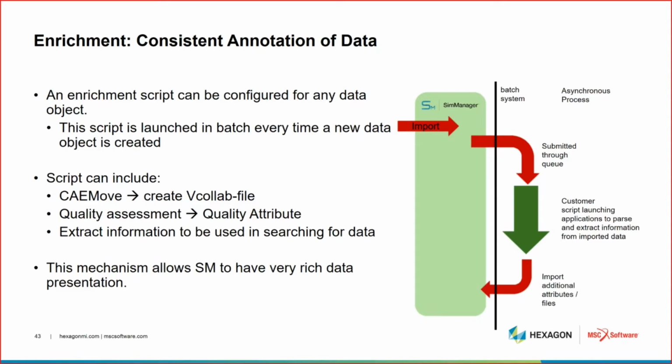But it might be something quite different. It might be just extracting some summary information about that model. So for example, for an input deck, how many loads, elements, and load cases have I got in this particular model of interest? Or maybe, and this is something that's quite often used in a multidisciplinary environment, if I've run, let's say, a thermal analysis for a particular model, I get a temperature distribution out of that thermal analysis. But often I want to be able to take that temperature distribution and then convert that into a set of temperature loads that can be applied to a structural model. Okay, so that's one example of the sort of connectivity between different disciplines and different items.